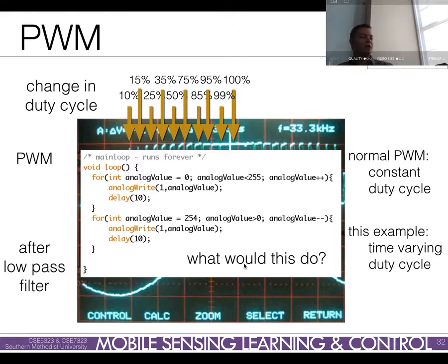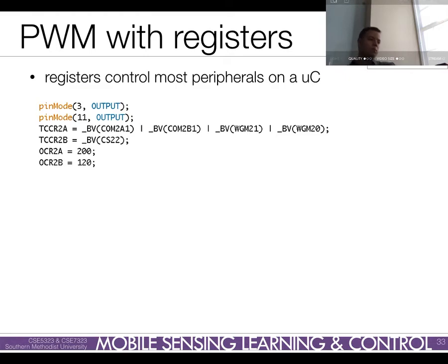All right. Basically, this analog write is expecting a digital to analog conversion. So if the analog output is 120, then it's going to try and output that analog value. Right? So 0 to 255 would be 0 to 5 volts. 120 is somewhere in between, like 2.5 volts or so. This is what it's going to try and just output constantly.